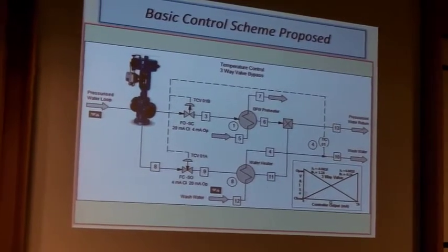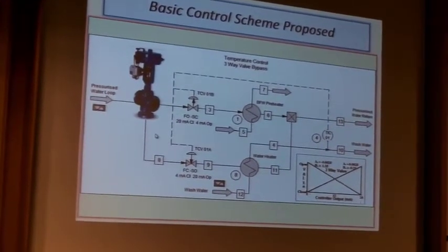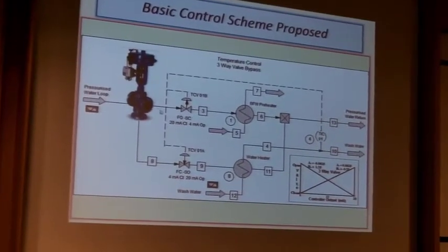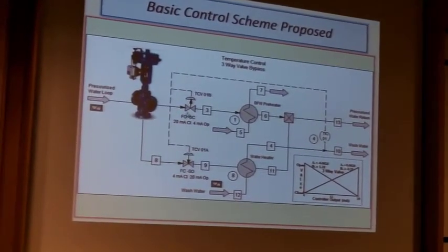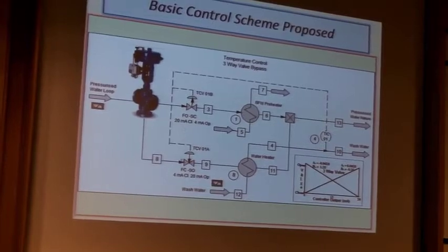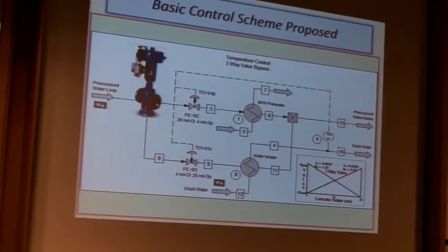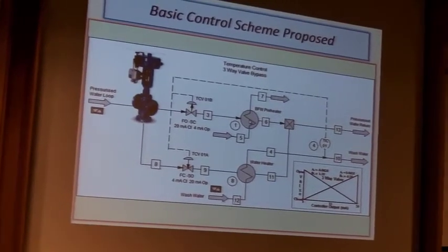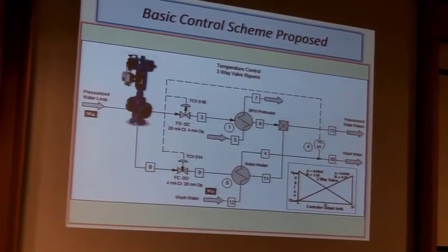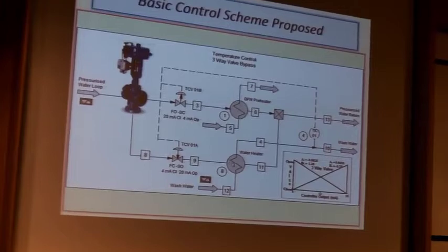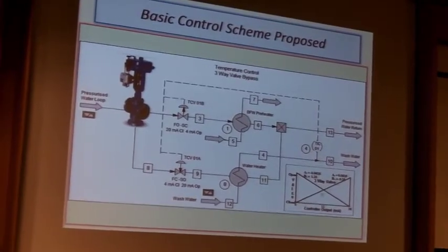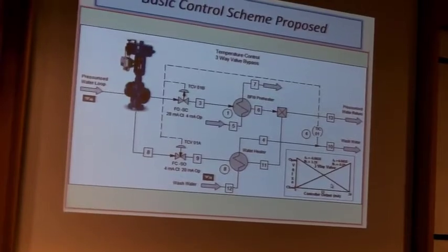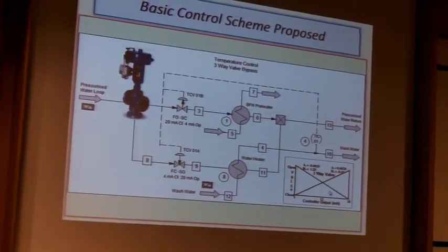So the answer was, that's basically the control loop. Three-way valve, as represented in the simulation by two control valves here, calibrated to represent that. Into one heat exchanger, which was preheating water to a boiler, and this is the water heater here. And we have the valves in split range, as shown there. So we can set that up in the simulation.